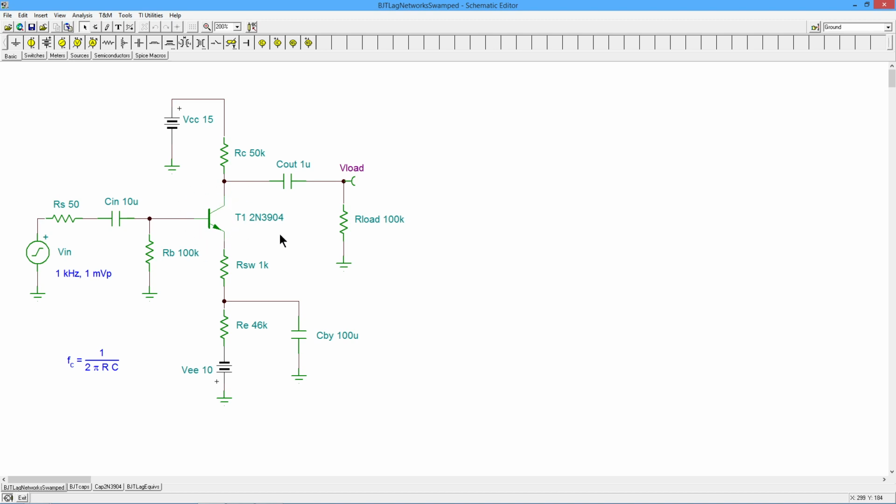Oh, and by the way, before I go any further, that's just for the transistor. In reality, there are small capacitances associated with all the resistors plus wiring. You might have an input capacitance for the following stage. Maybe you have some coax cable out here. That could have 20, 30 picofarads per foot. So these things can add up. But let's focus in on this transistor.